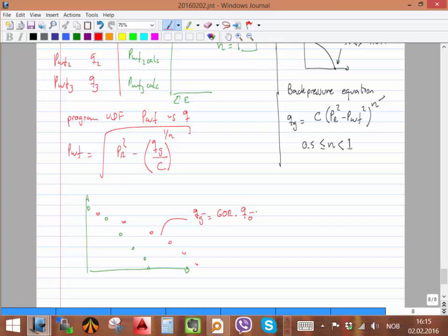But sometimes it could not be the same. The GOR and the water cut don't stay constant for all the points. What case might you think that might happen? What could happen that the GOR at point 0.1 is different than the GOR at 0.2? Because you have the free gas producing and its mobility depends on this drawdown. A simpler case: let's put a horizontal well, producing from a very thin oil rim, and we have a very big gas cap.